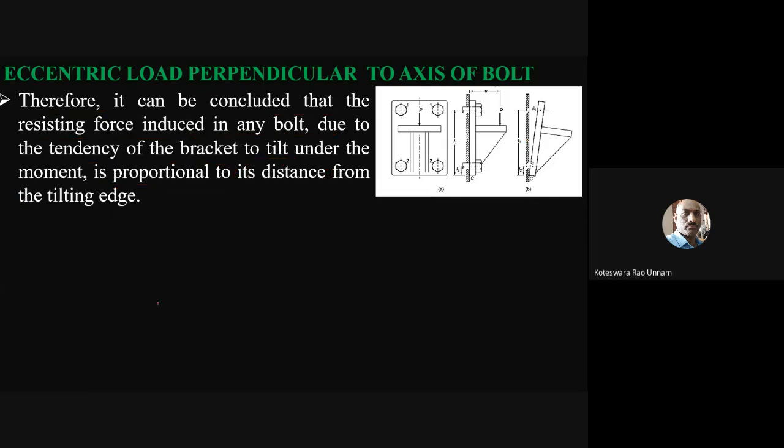If I assume that, then again the same relation applies. The force due to this bending moment in the first set of bolts we take as P1 double dash, which is given by C into L1, where C is the proportionality constant, and P2 double dash is C into L2. Now if you write the equilibrium equation, P into E is the moment. One force acts here, P1 double dash, and the other force acts here, P2 double dash.